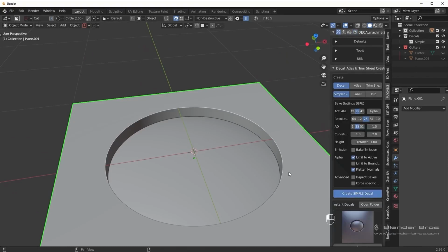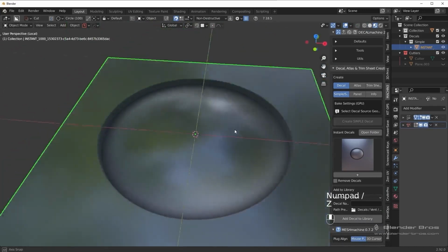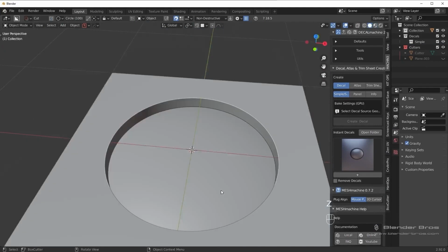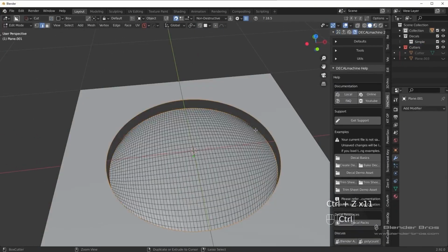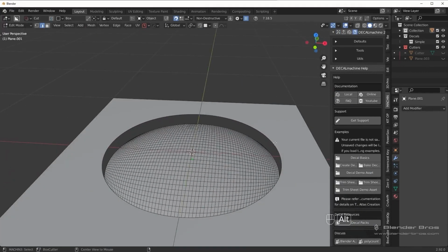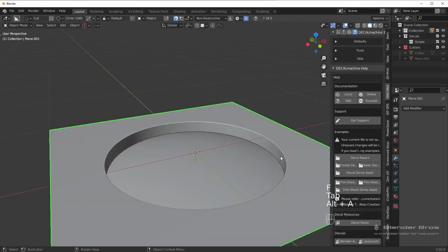This is exactly the process I take to diagnose decal issues, because they happen a lot and oftentimes they're really annoying to deal with. And as you can see, we still have a problem here. So it looks like rebuilding that surface didn't work either. So the next potential fix I would use in this case is to try baking this thing solo. So extrude this down, just fill it in, and I would try baking this thing right here solo.